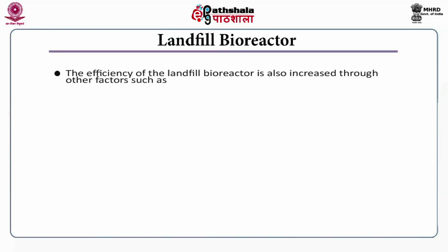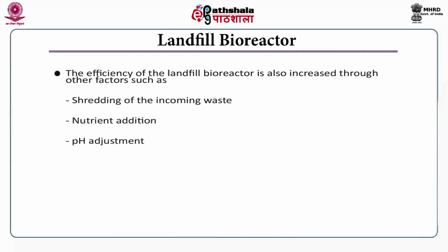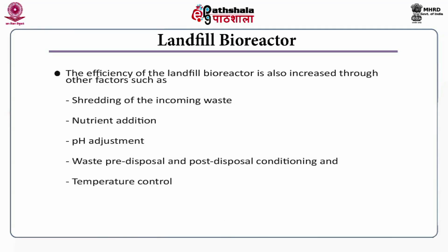The efficiency of a landfill bioreactor is also increased by other factors. Shredding will improve the degradation and accelerate its rate. Also, you can add nutrients through the incoming waste stream or through other modes of maintaining moisture. You can adjust the pH, and waste pre-disposal and post-disposal conditioning and temperature control will also act as factors to accelerate the rate of degradation within a landfill bioreactor.